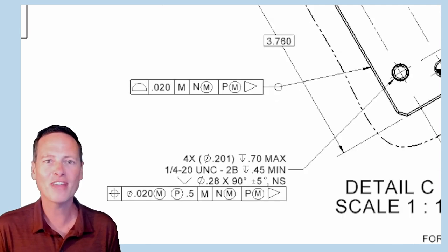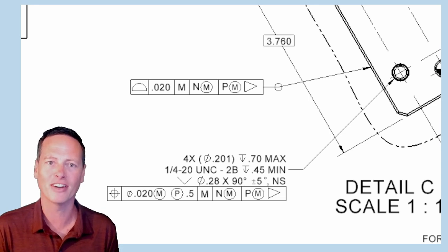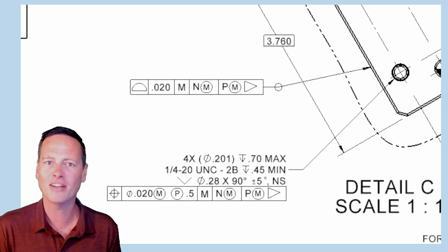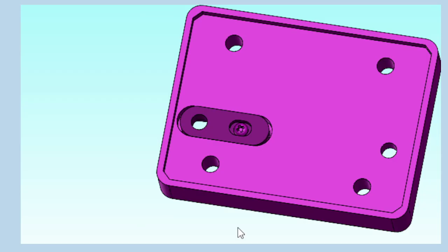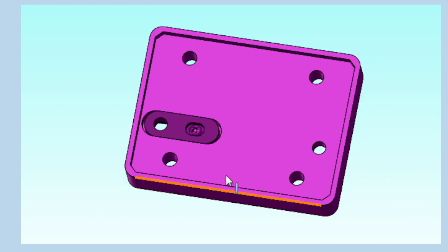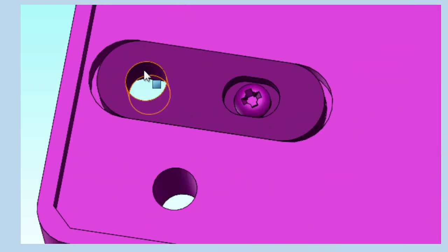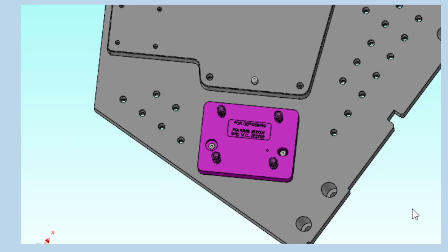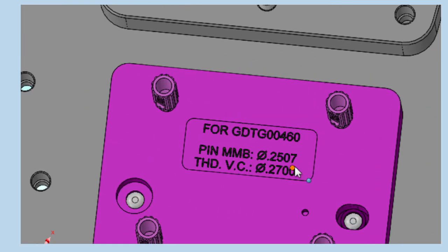Okay, and here I told you that it was a good idea to have that perpendicularity because now, with translating datum modifier in all my datum P tertiary references, we could start using a gauge that has a translating datum P simulator, in this case, sliding within a groove. And because of that, we can start calculating maximum material boundary as the MMC size plus perpendicularity tolerance to get us to a place where both of these holes are the same size now, 0.2507 diameter.